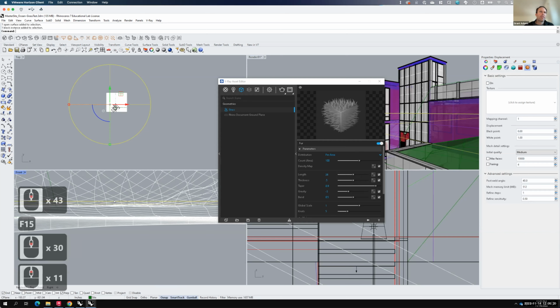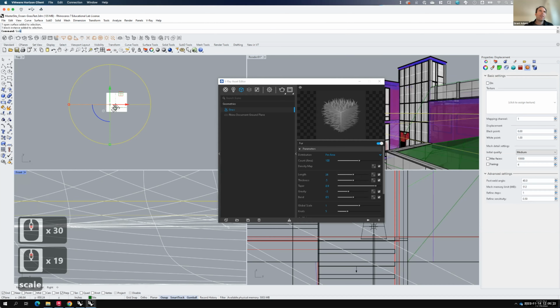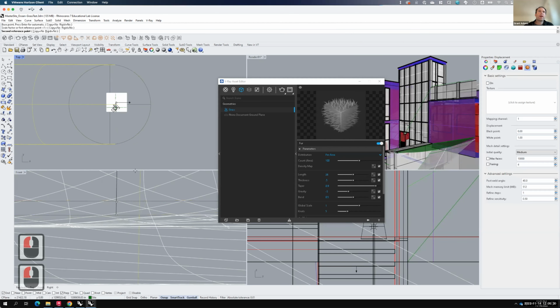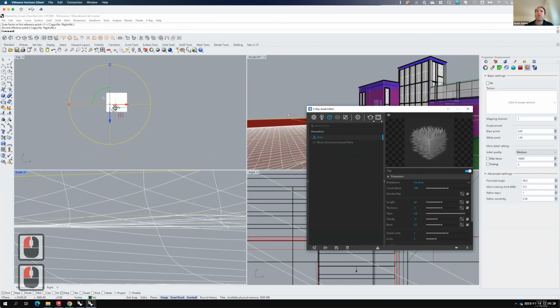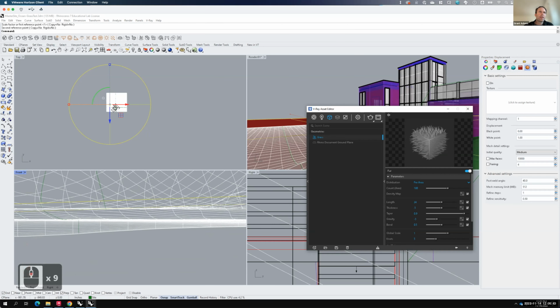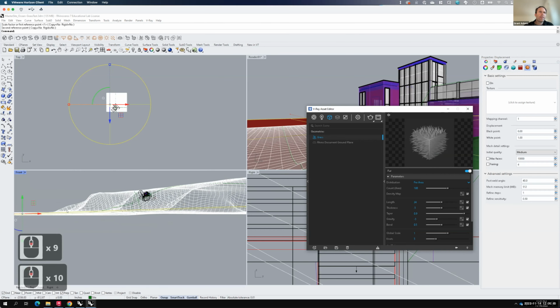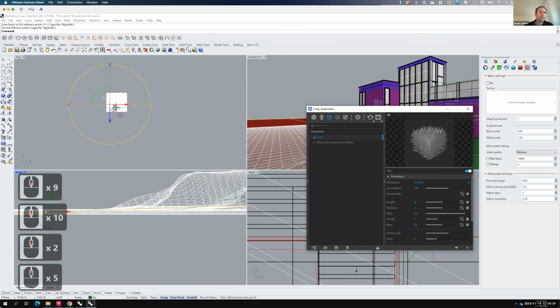So let's go here. I'm going to type in scale 1D. And what I'll do is stretch where the horizon is on that plate a bit, bringing it up over where that line was. So let me back up here a little bit more. I should have done it right here.